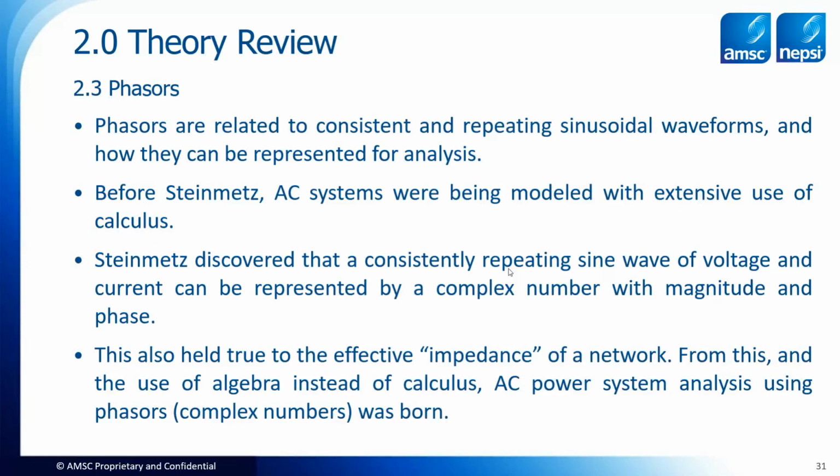Before Steinmetz, AC systems were being modeled with extensive use of calculus because no one had developed this analysis method yet. Steinmetz discovered that this consistently repeating sine wave of voltage and current can be represented by a complex number with magnitude and phase: the phasor. The phasor is nothing but a complex number.